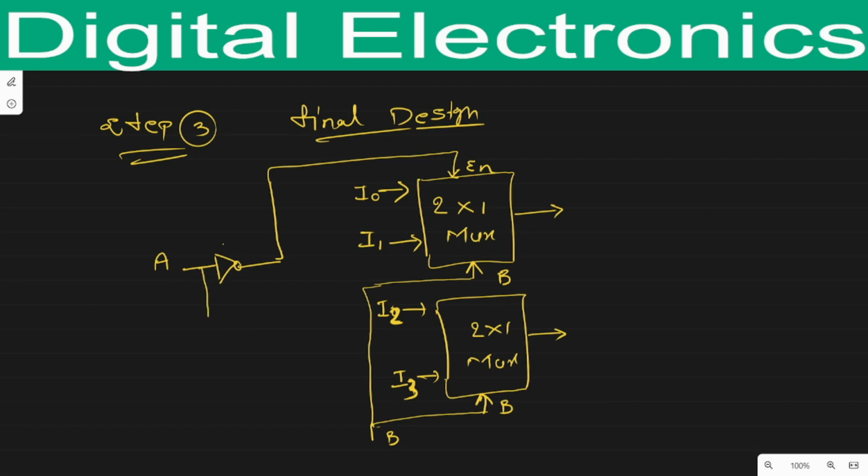Okay, we will connect next into the second multiplexer. Now what happened? There are two selection lines. A and B will act as selection lines. Four inputs are there, but here there are two outputs. So to find one output, I will take one OR gate here. This OR gate will provide me output O.